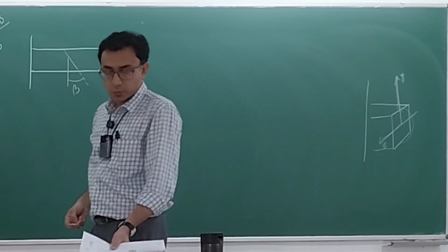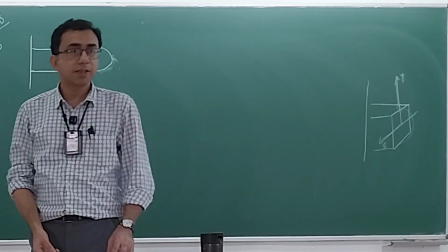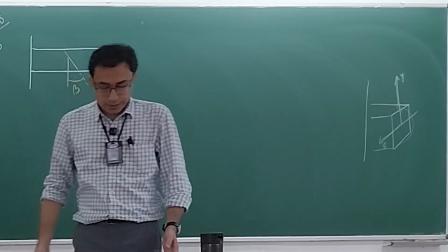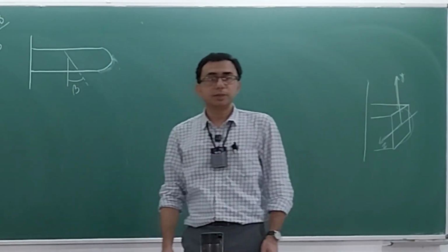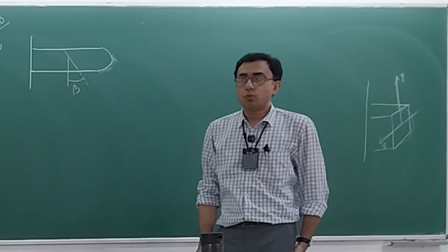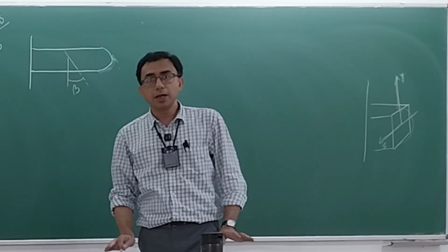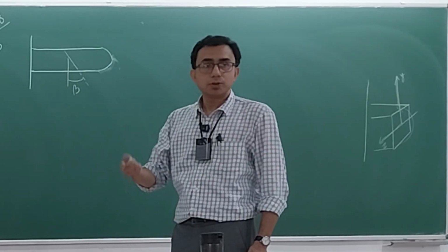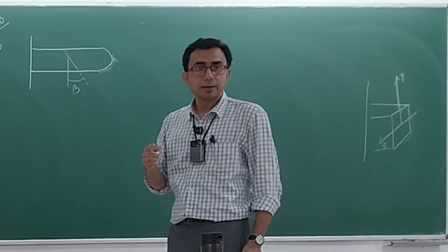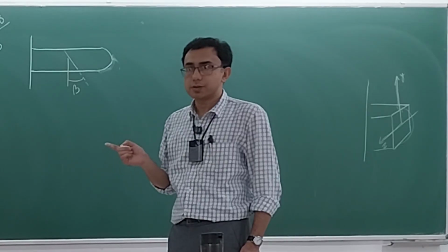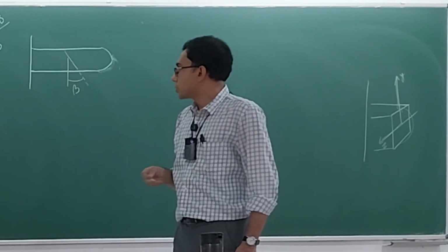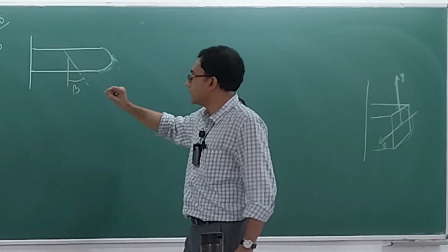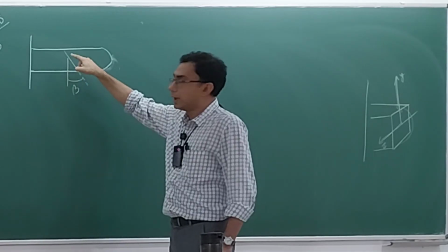Now the question is pressure. Pressure we have to find out. But how do we connect all of these things together? What are the things that we have learned in the context of pressure vessels? We have learned about the hoop stress, sigma 1, and the longitudinal stress, sigma 2. Suppose we focus our attention at any point along the weld.